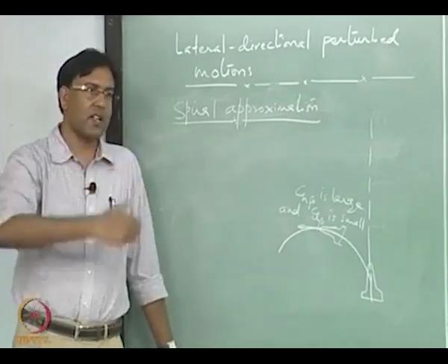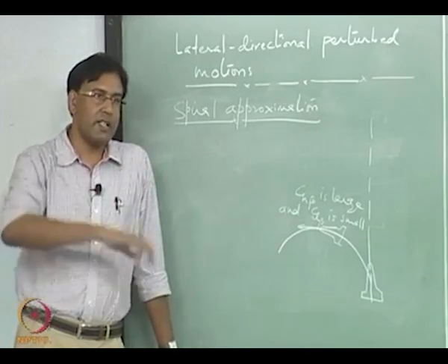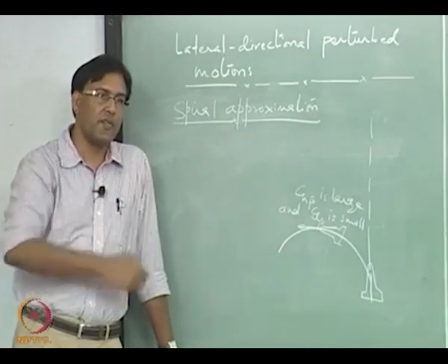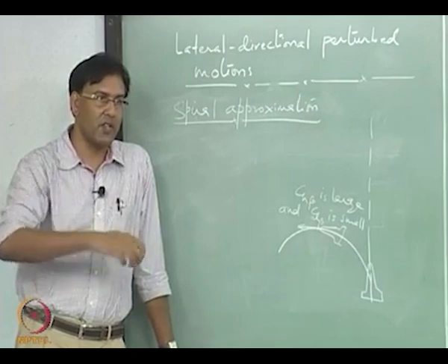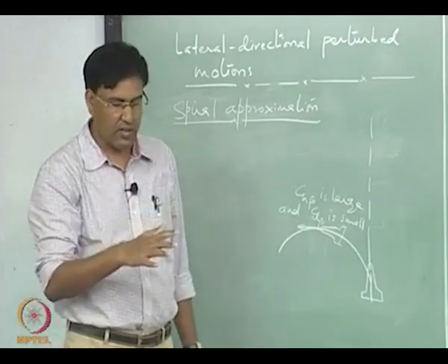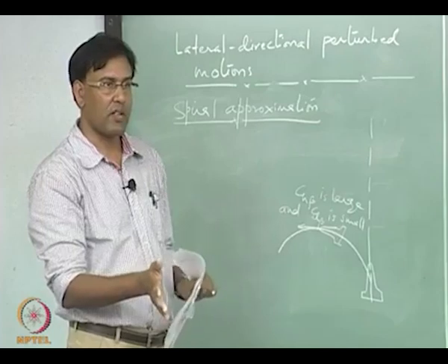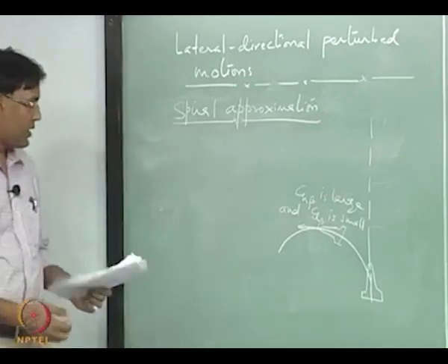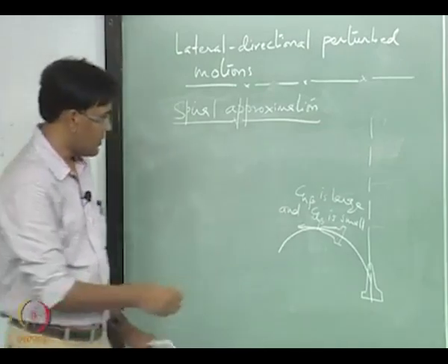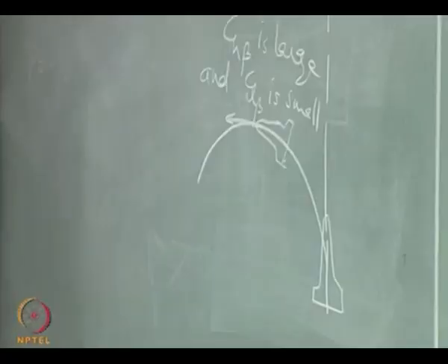We have understood that, right. Whenever there is a change in bank angle, the lift produced will not be enough to balance the weight. So, it will start banking, and it is also going down, and that is the spiral divergent motion. Okay, in a critical case, it can also take a dive, that is called a spiral dive.